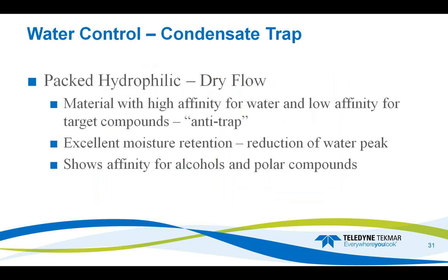Okay, so this brings us to packed hydrophilic condensate traps. And these use a material that has a high affinity for water and ideally a low affinity for our target compound. So you can think of it as like an anti-trap as compared to our analytical trap, where we choose the adsorbents so that they have a high affinity for our target compounds and a low affinity for water.